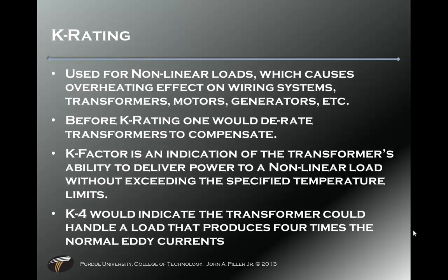Alright, so what's a K rating? K rating is used for nonlinear loads that cause overheating effects of the wiring systems and transformers and motors and generators all across the board. Before K rating, we would just derate a transformer to compensate.